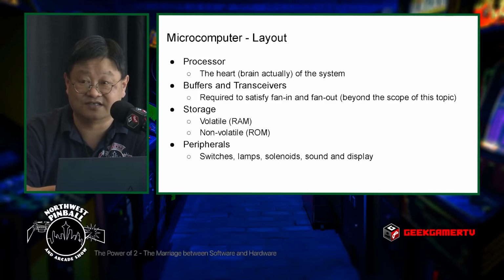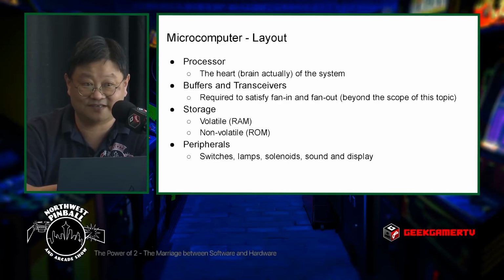A lot of the System 11 address decode was embedded into that big 84-pin WPC ASIC, and it's a black box, and you don't want to know about it because you can't see inside it. You can see inside it on a System 11 board, which is why I want to spend some time covering it, because it's easier.